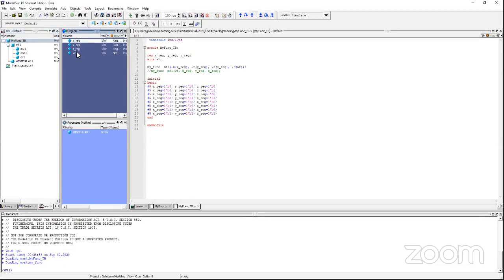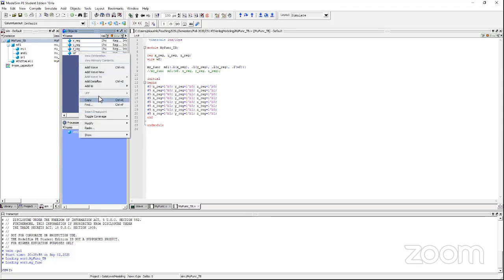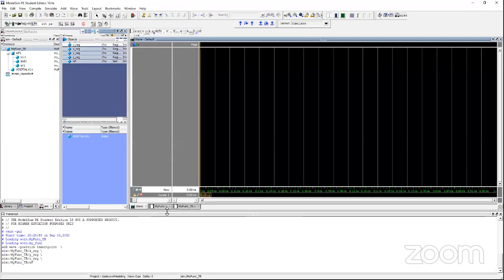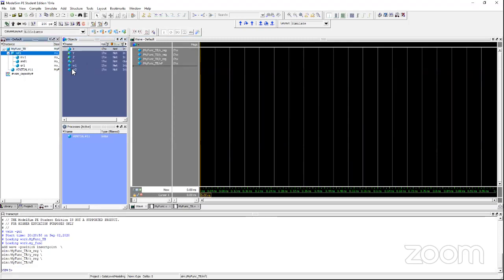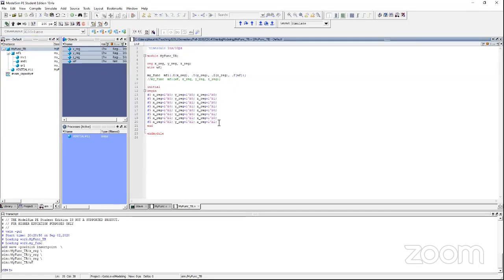Let's observe it. Okay. So what we do is select all, like you can hold the shift key and just move over the mouse there, right click, add wave. So it will be added onto the wave. And in fact, you can actually go inside and look at its own wires value for the debugging if needed. But let's not do that right now. Let's stick to this one. And then, oh, I wanted to do one more thing we need to do. Otherwise, we won't stop it.